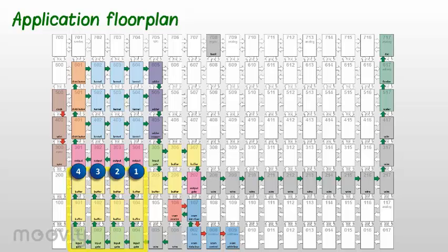Numbering the buffers from right to left, 4 reading sequences are used, specifically 1, 2, 3; 2, 3, 4; 3, 4, 1; and 4, 1, 2. The data ordering in the stream is ensured by buffer output gate nodes and distributor nodes, which feed the buffered data into the convolution kernel. Thus, the kernel receives 3 consecutive bitmap lines simultaneously from left to right edge of the image.